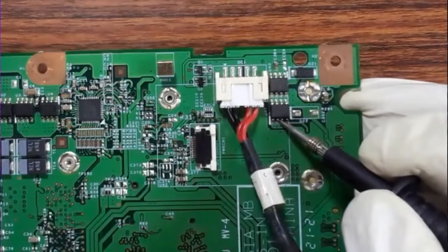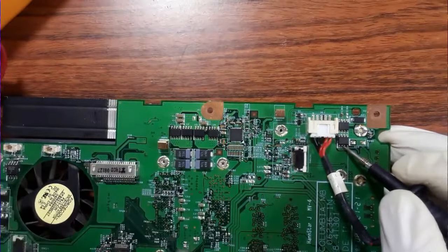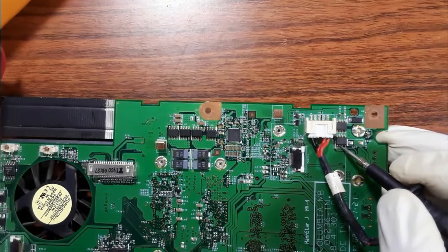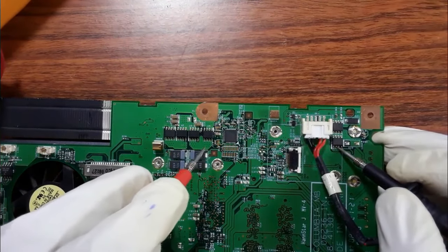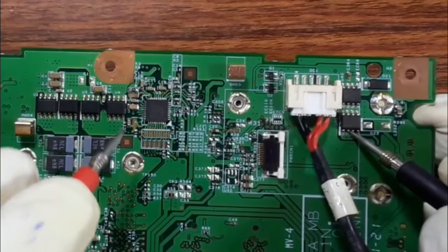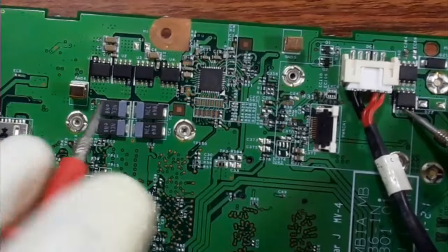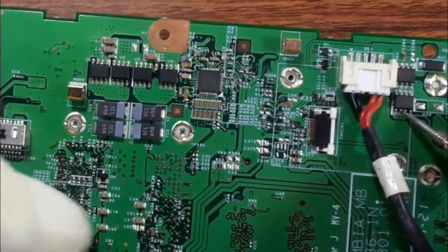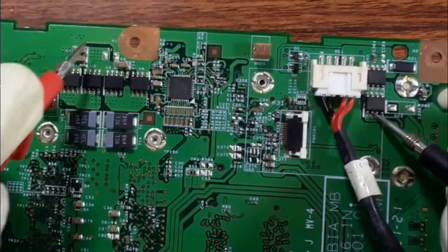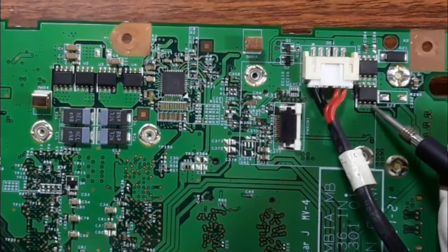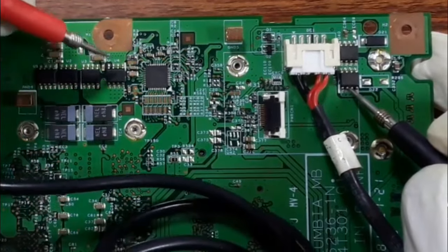Now, from this switch, as you can see, the 19 volt will be distributed to the whole motherboard, to the big or important circuits in the motherboard. For example, this is one circuit. This is the circuit of the processor, because we have the fan here. So the processor is in the back of this. In the back here we have the processor right in the back. So this is the processor circuit. Normally, the 19 volt will go from here to here. So let's check all these MOSFETs.